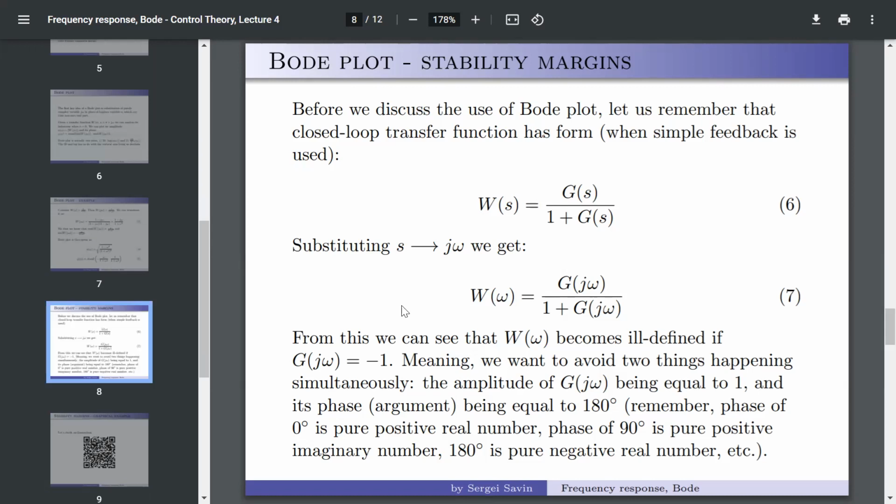So here, when we consider the function g, we are not interested in the actual function itself, but only in the fact that it gives a complex result. We're talking about amplitude and phase. What do you mean we are not interested in the function itself? I mean when we are considering the condition when g of j w is equal to -1.